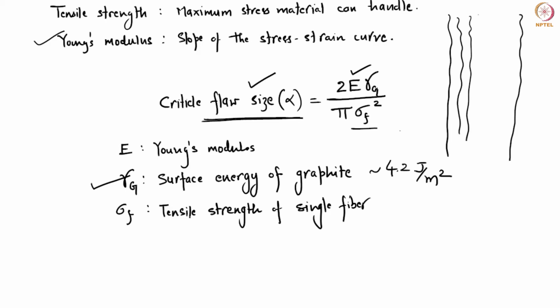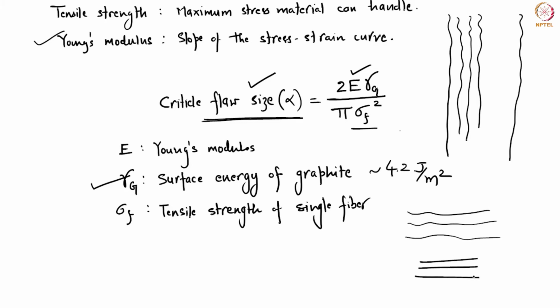Why does that happen? What happens is, in the beginning, when you've heated your carbon polymer fibers to about 1000 degrees, at that time what you have is these turbostratic carbon sheets. What are turbostratic carbon sheets again? These sheets are also graphene-like, but they contain several defects, and therefore they are not organized in an ABAB fashion, as in the case of graphite.